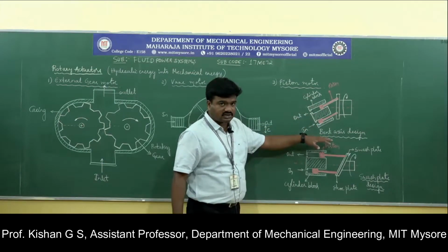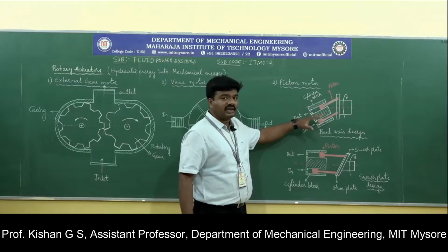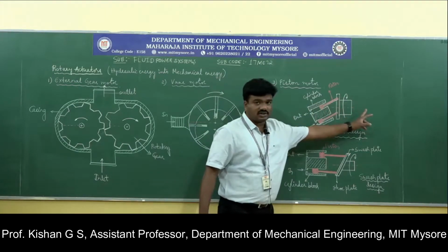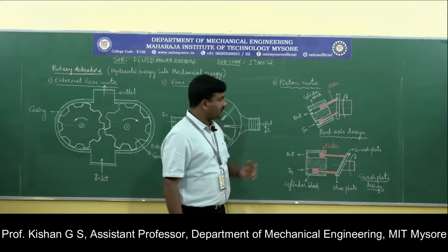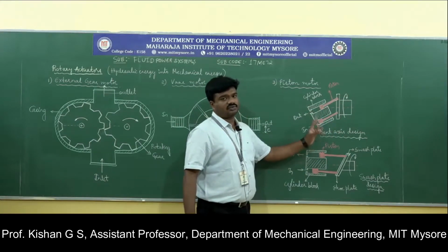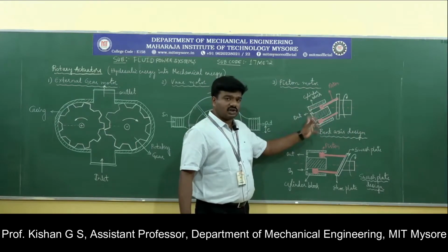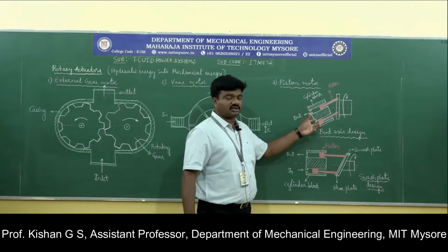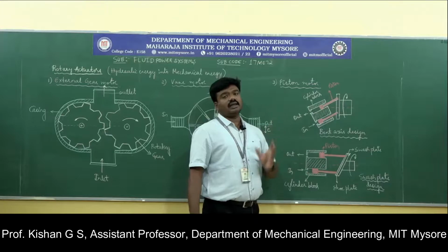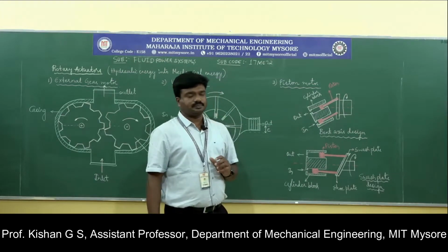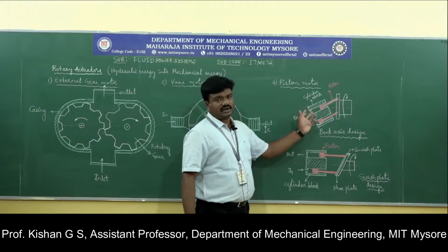motor of bent axis design, which consists of a cylindrical block bent at an angle of theta with respect to the horizontal reference or the axis of rotation of the drive shaft. The cylinder block consists of multiple pistons which are arranged such that the rotation of pistons along a particular direction in the cylindrical block is achieved due to the input, that is hydraulic energy. So we have the inlet and outlet which are assigned here.